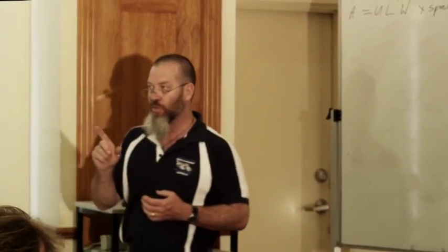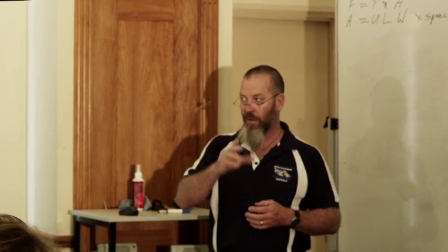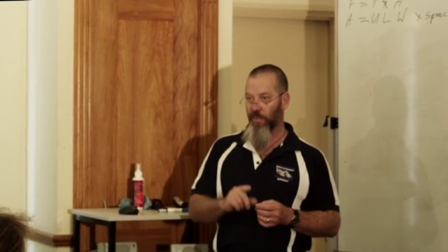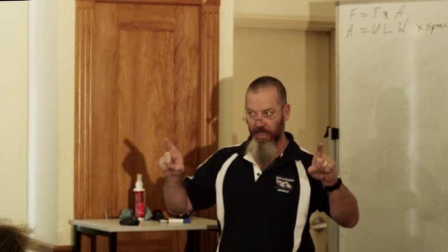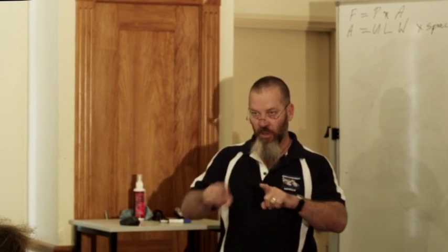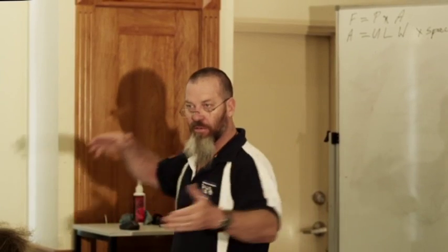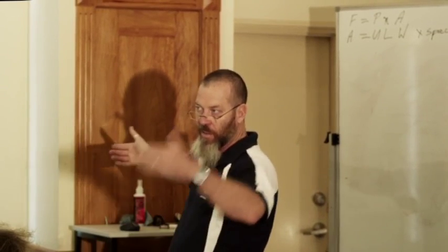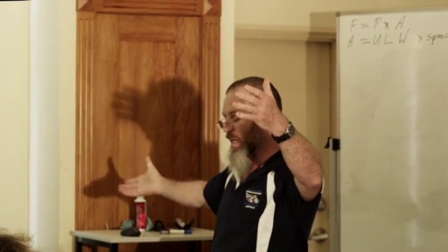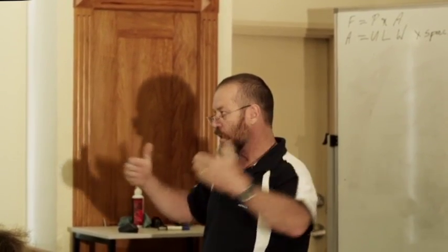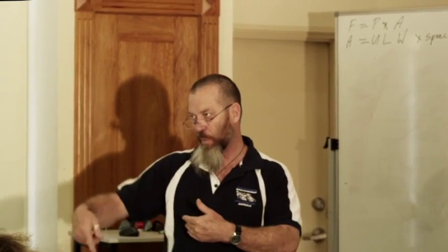You don't have to do that on every rafter connection, and I'll show you how you play with that later. Remember what I was talking about before about the distance between connections? The ULW is half the distance between the underpurlin plus half the distance between the underpurlin, which gives you the spacing. The spacing is the distance apart you put those.